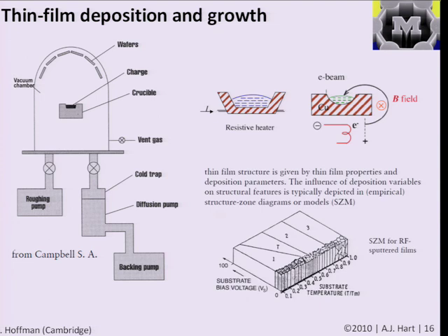And in general, the structure of the film that you end up getting on the substrate is going to depend on all the deposition parameters that you might have. The vapor pressure of your precursor in this atmosphere, the temperature of the substrate, the pressure of the chamber, and so on. And back in the day, in terms of studies of thin film growth, there's a lot of relationship developed between the process conditions and the structure of the film.